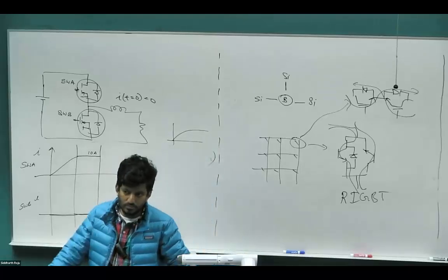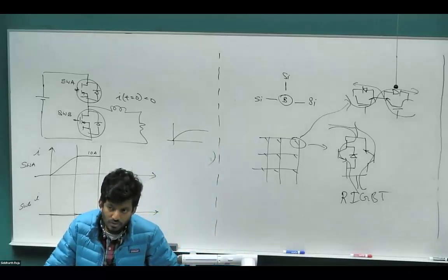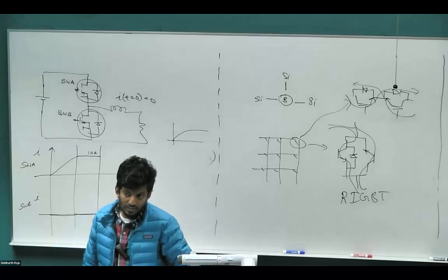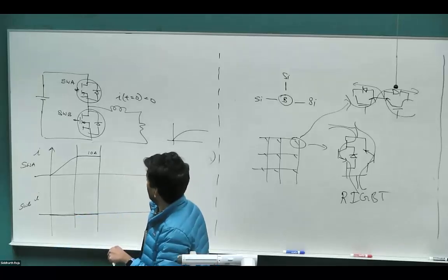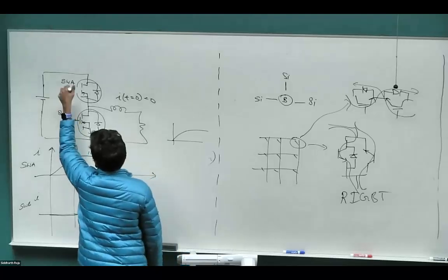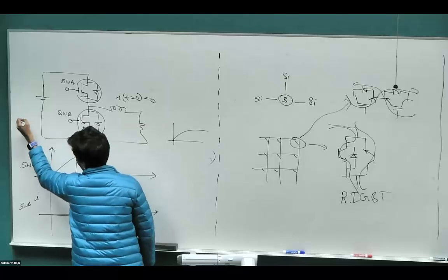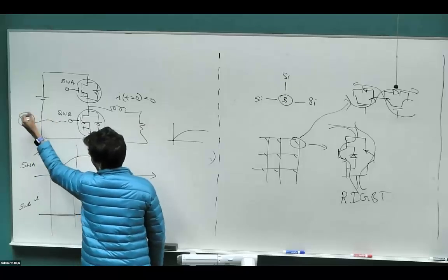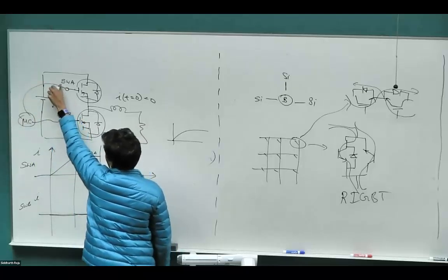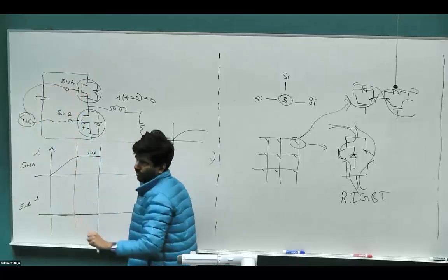Why are the gates unconnected in your drawings? Like on the MOSFET, there's nothing going into the gate. Oh, this is the gate that needs to go double. So this would be controlled by some kind of microcontroller or something. It's a little bit more complicated because you need some kind of isolation between the microcontroller and the top switch and so on and so forth.